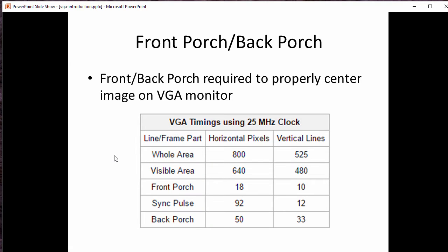And then there is one last concept to talk about, which is front porch and back porch. Now, VGA is a little bit frustrating in this regard, in my opinion, because front porch and back porch are basically required to center the image on a VGA monitor.